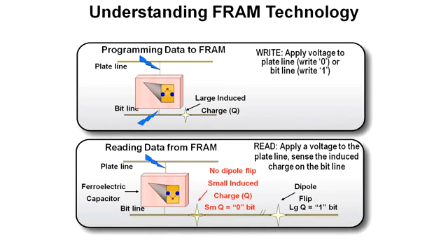In the process of reading the data, the crystal that's polarized in the direction of the applied field loses its current state. Hence, every read needs to be accompanied by a write back to restore the state of the memory location. This is inherent to the nature of the FRAM memory and is completely transparent to you, the end user.